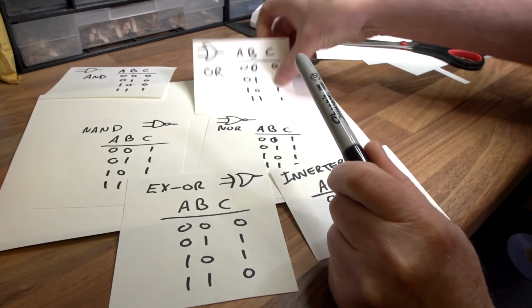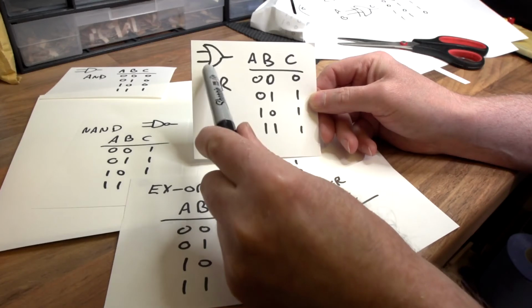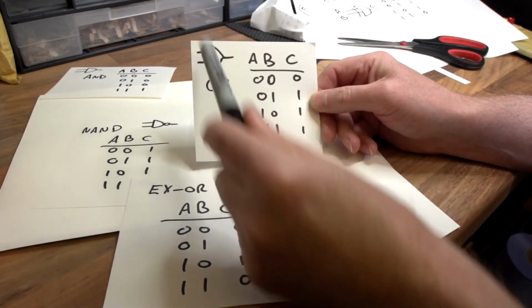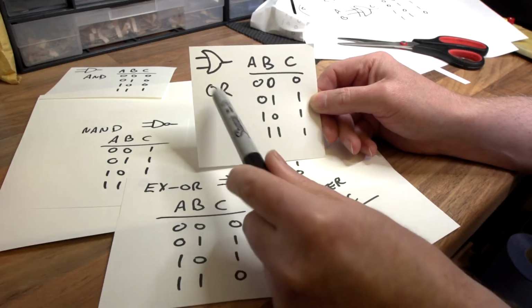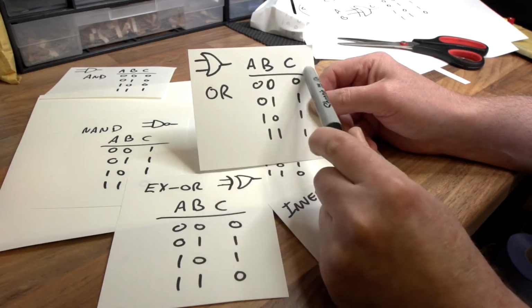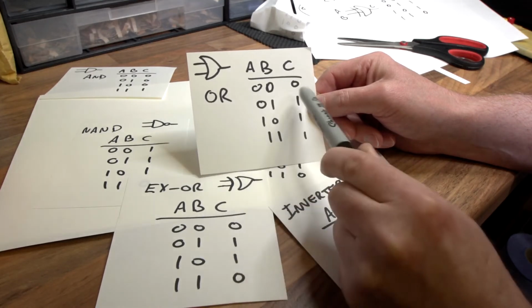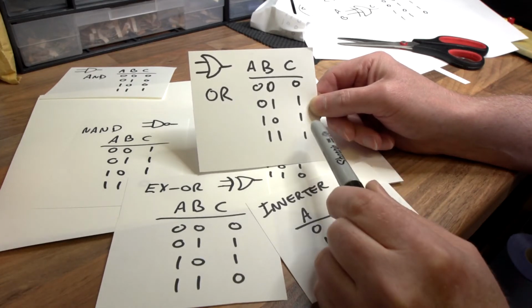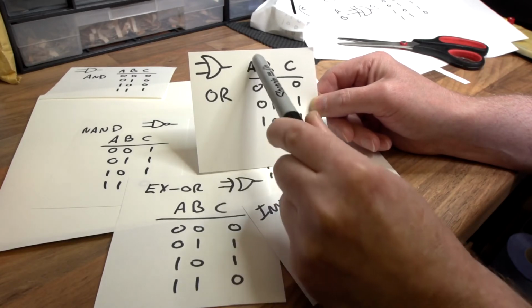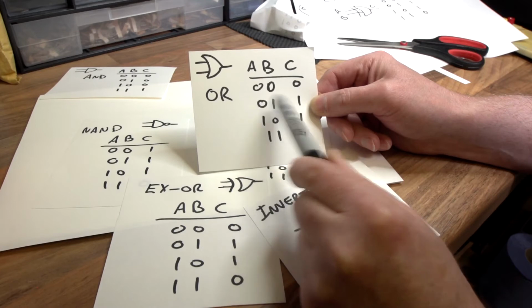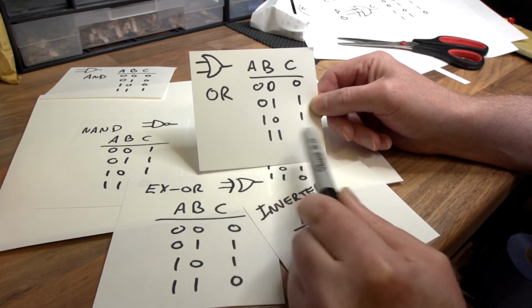Then we have the OR gate. And with the OR gate, that's the symbol there with its curved input front. The AND gate was flat, if you remember. This one's different, to show it differently on a schematic diagram. This is the OR gate. A and B the inputs again. C is the output. Now with an OR gate, if any of the inputs are on, then you get a true 1 output. It's only when both are off that you get a 0 output. So A or B can be on, or both together, doesn't make any difference.